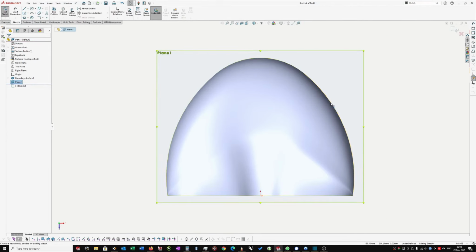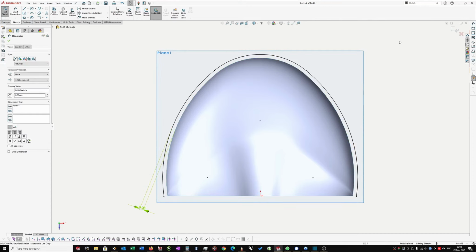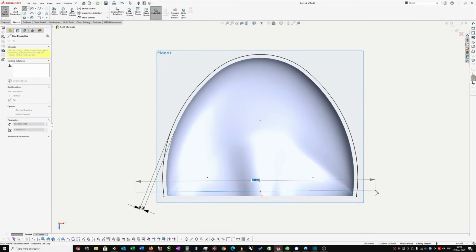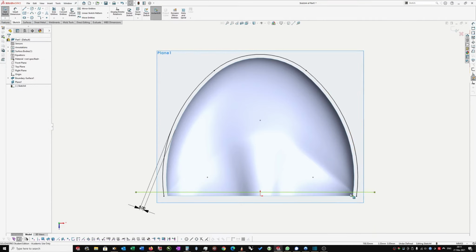And when I'm in here, I want to offset these 3, holding the shift button down. I'm going to offset them by, so let's say 8 millimeters. Just think about that for a second. Is 8 enough? Yeah, it should be. You guys can tweak it if you don't like it. Alright, so while I'm in the sketch, that's going to become the basis for the outside wall around the 3 sides, but I can also create the sketch which goes across the front, which I'm also going to create like this. So I could use a straight line.